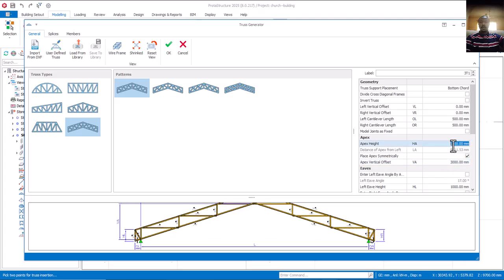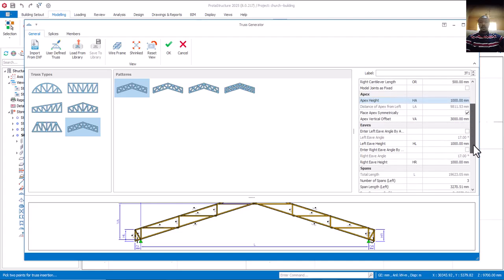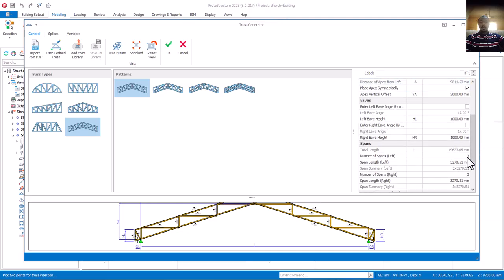So let me click somewhere else. Okay, that's fine. Okay, so the next thing, let me scroll down. I will now scroll down. This place we are now seeing a truss. This truss, if you now look at under the truss where we are talking of a span length, you can see that we have a 3270, and this place stands for the distance between the purlins. Is that okay? From one purlin to another.